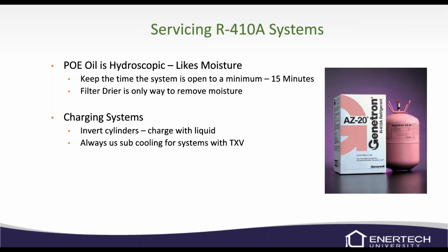Obviously, we want to charge in a liquid, and we'll normally use subcooling when we're charging it. If you don't have an IOM, you're trying to charge one of our units, a good thing to always remember is if we can get close to 10 degrees superheat and 10 degrees subcooling, we should be pretty good. Now, we're pretty good about listing what our ranges are in the IOMs, but if you don't have one or you've got an older unit, just try to remember 10 and 10. 10 degrees superheat, 10 degrees subcooling.